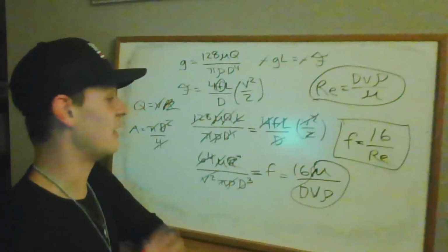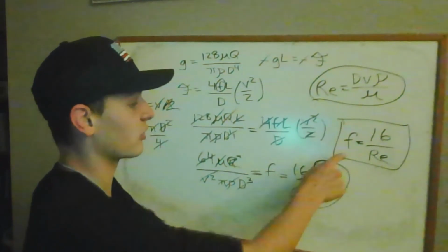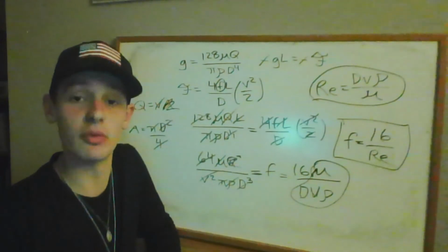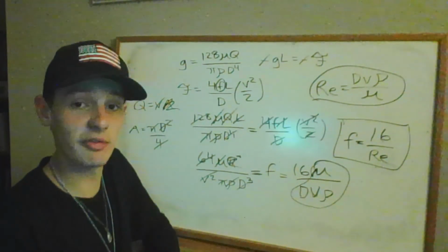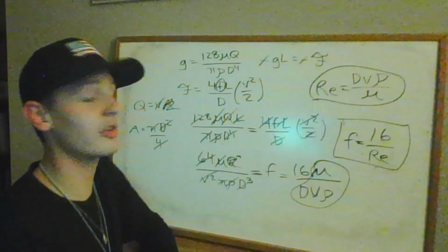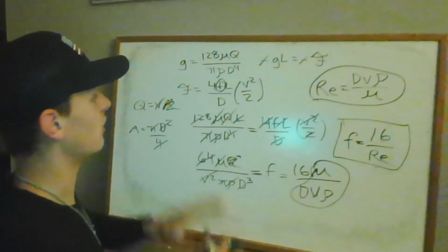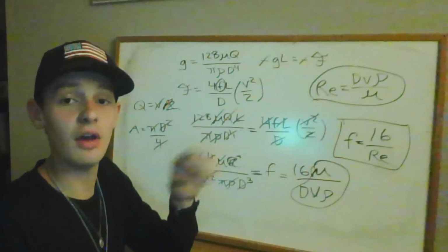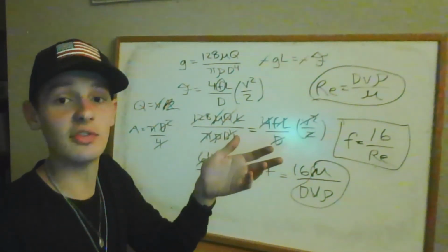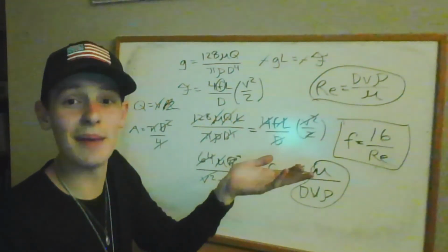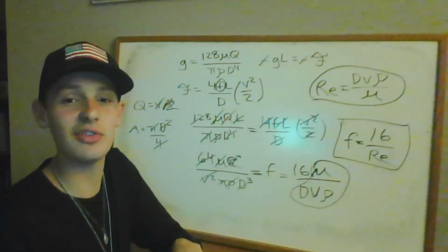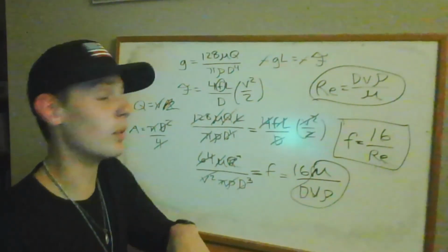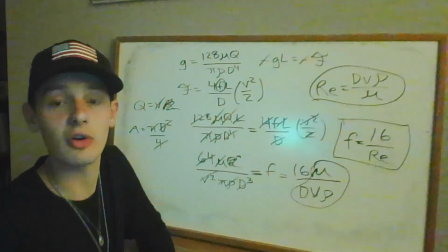But again, if you want to have this written down, this expression, the Fanning friction factor, is equal to 16 over the Reynolds number for laminar flow in this situation. We could have also derived this looking at a horizontal cylindrical pipe and looking at the control volume. In that case, you would be looking at a pressure drop due to the frictional heating, which emanates from the viscosity of the fluid. And in this video, I just chose to go with the vertical cylindrical pipe.